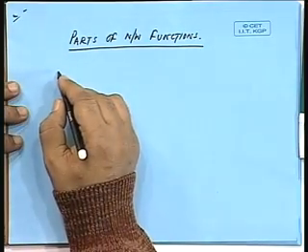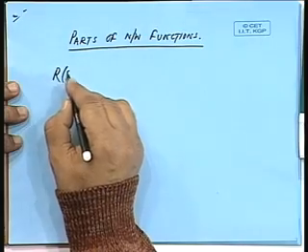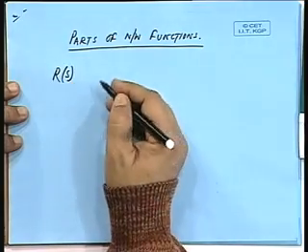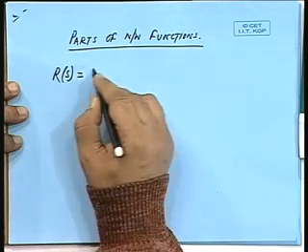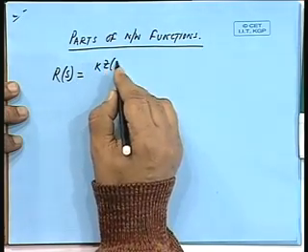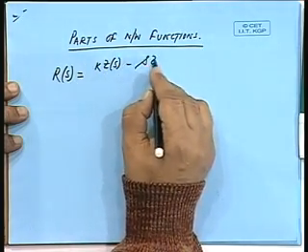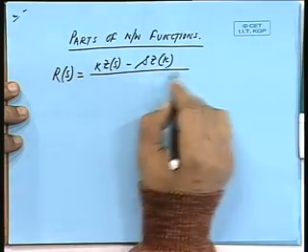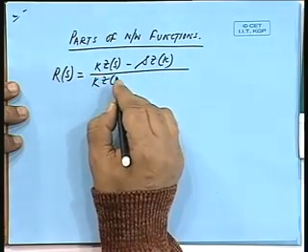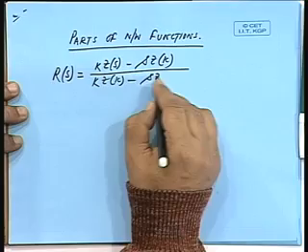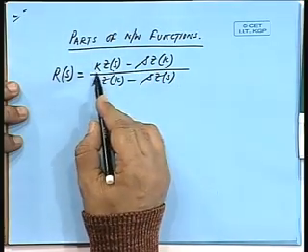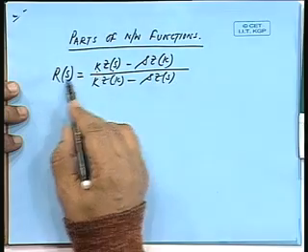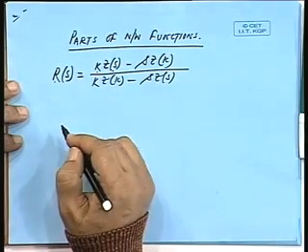So, in the Bode-Duffin synthesis, we defined the Richard function, which is a positive real function in terms of Z(s), as R(s) = (k Z(k) - s Z(s)) / (k Z(k) + s Z(s)). If Z(s) is a positive real function, then for all positive values of k, R(s) will also be a positive real function.